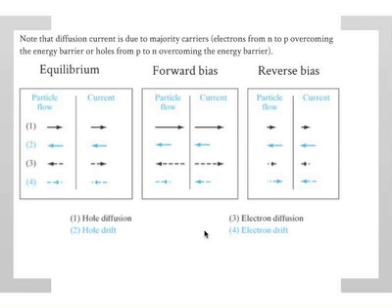When you apply forward bias, you can see qualitatively what has happened. You have reduced the barrier for diffusion. So again, you've injected more holes from P to N now because you've reduced that energy barrier. So this current component increases. The drift doesn't change much, and we'll talk about that in a little bit, because the field hasn't really changed dramatically.